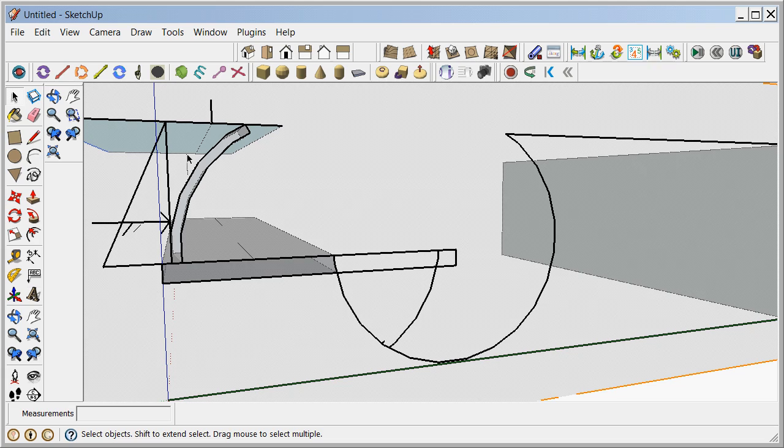So by adding the resultant of the triangular pressure distribution, the resultant of the weight, and the resultant of the potential if you had any kind of overburden above, you add those three vectors together. That gives you a magnitude and a direction. You just do that so it runs to the center of the circle, and you solve the center of force, or the center of the hydrostatic pressure.